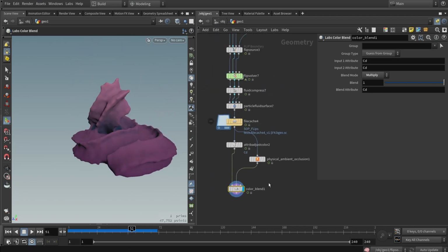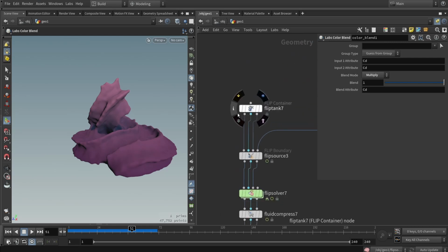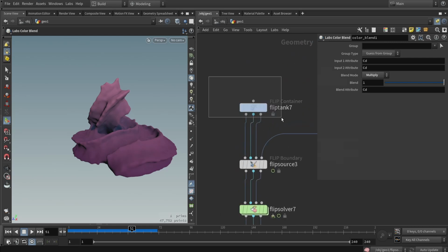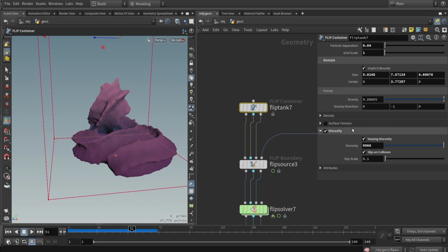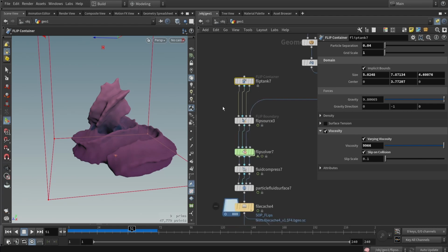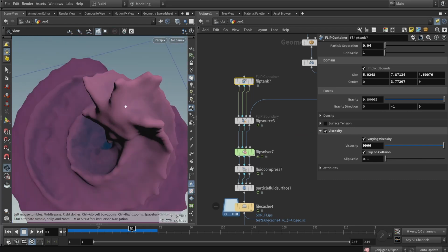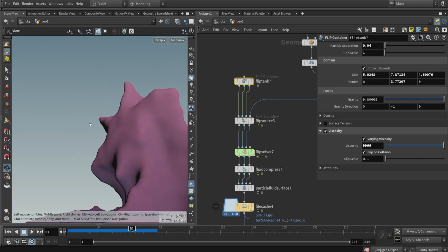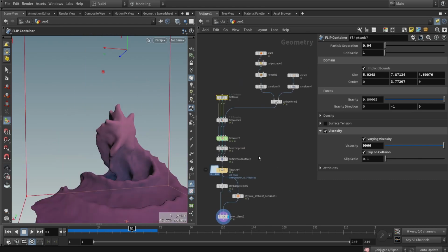And of course, the main thing that I also forgot is the viscosity settings. So you can just, in the tank itself, enable viscosity here, and you can put this to a very large number, and then it will actually stick to each other instead of splashing out. It will just stick, because that is what viscosity is doing. It will make sure that everything sticks a bit more in its original shape. As you can see, you can see the star shape roughly here. So it's roughly this setup, showing you some other elements you can do with this thing.